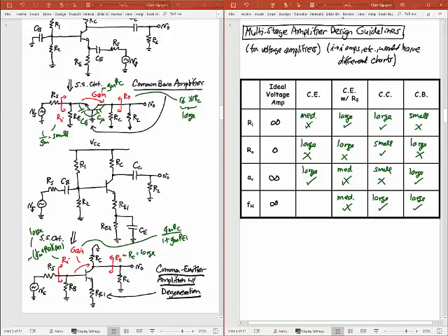You get even larger if you put that same transistor in an emitter follower. So the problem is that in the common emitter you have a lot of gain. So you take C mu with the Miller effect, you're multiplying it by that gain, and that's killing your frequency response. So it actually has a small, compared to the other configurations, frequency response.